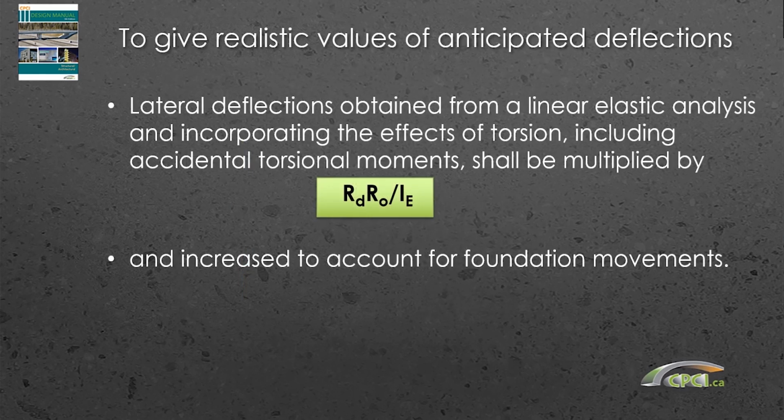And then just a reminder to everyone, even though you've done a lateral load analysis on your computers or however you're doing it, the deflections that you get out of your analysis, you still have to multiply by RD/R naught over IE. So just a reminder that you need to magnify your deflections from your analysis to get realistic values of the deflections in the earthquake.